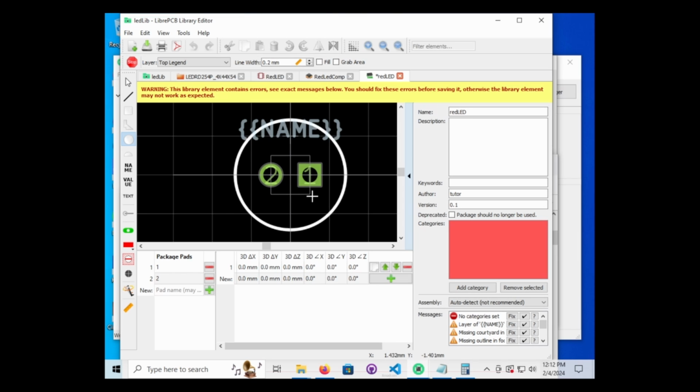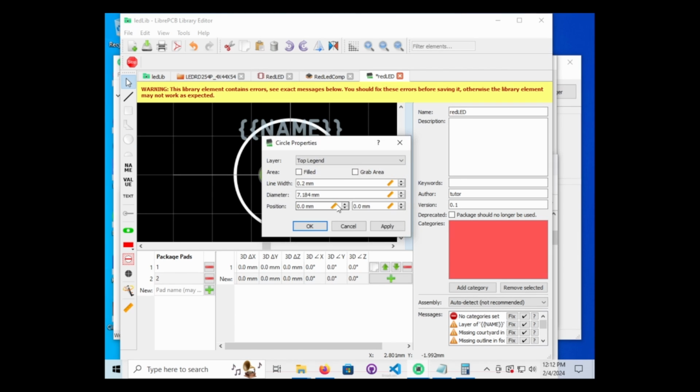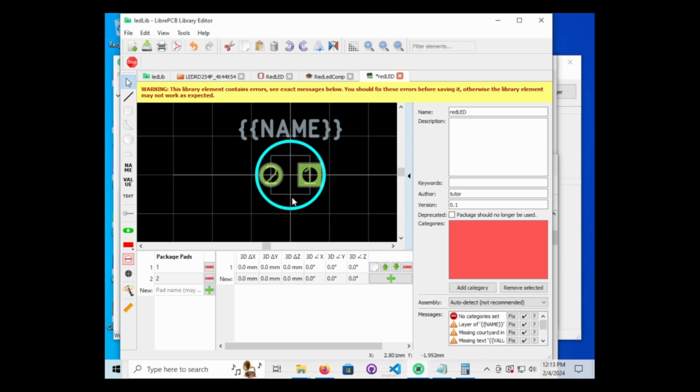Alright, now we're going to add the outline for the capacitor, about how big the capacitor goes out. This will be on the silk screen layer and on the top package outline. No, it should be top courtyard. There we go. So their names are a little different. I usually do it on the top courtyard layer, because that will be printed with PDFs.